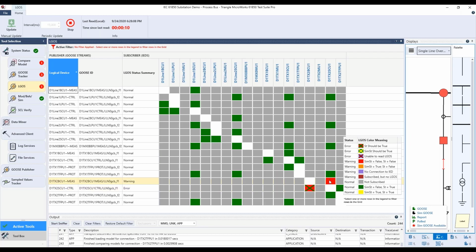And by coincidence, this is the same device that is also not sending. So I would suspect here is a problem with the configuration of the Goose port on the IED. So that gives you an idea what could be wrong. And then, of course, you need to go into the IED configuration and analyze what is wrong there. But from a system perspective, we can track that down and we see where we have apparently a problem.